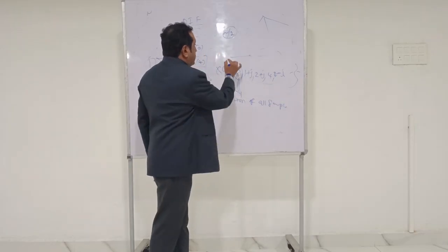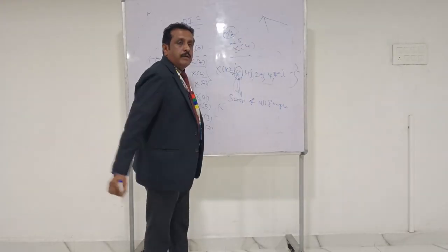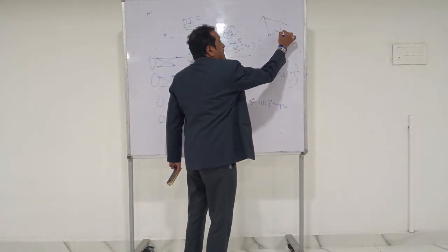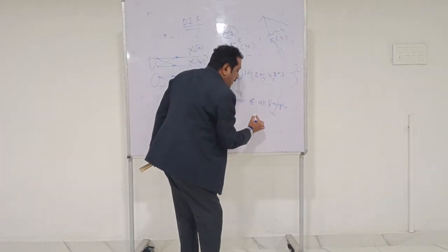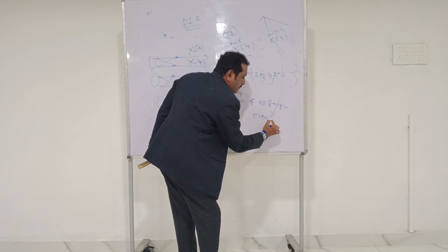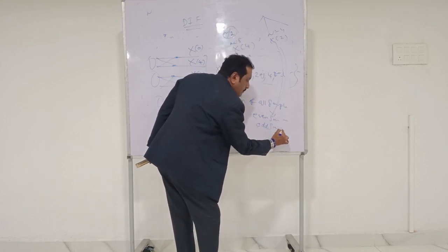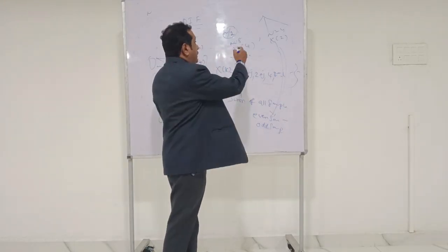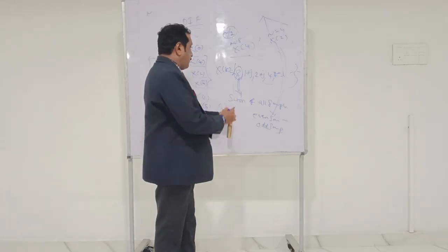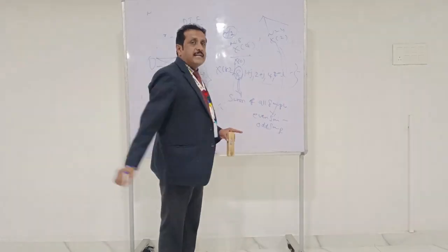And the middle sample, for example, when n is 8, your middle sample is X of 4. If n is 4, your middle sample is X of 2. The middle sample answer will be equal to the sum of even samples minus the sum of odd samples. And the remaining pairs, X of 1. Now we know the procedure for checking capital X of 0 and capital X of 4 for n equal to 8.